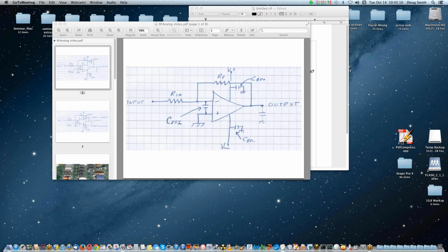Okay, the one thing to be careful on shielding, metal cans are nice. If you have to open up the top of the circuit board, expose the underlying ground layer, solder it down to that, and then every lead coming in and out would have to be bypassed. Since we're probably talking about op amps that are relatively low frequency, bypassing for 2 gigahertz signals is probably not that hard to do. Then you do have a thing.